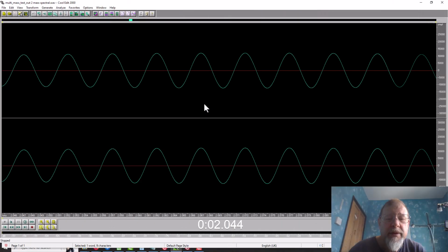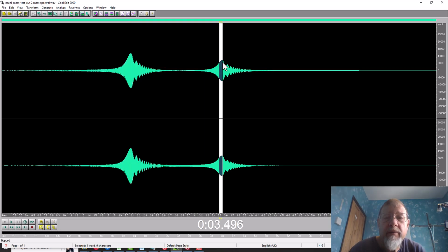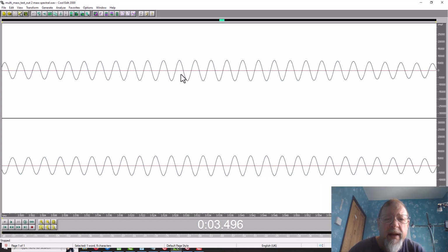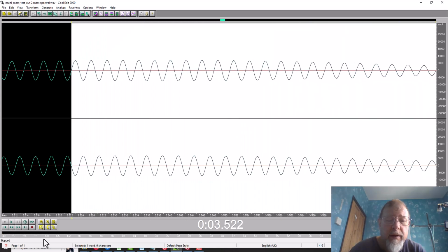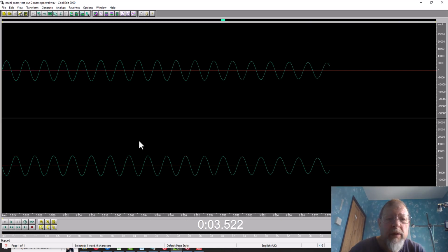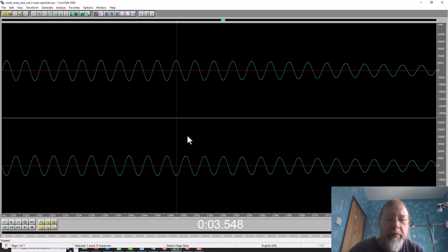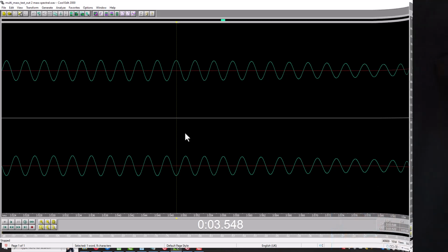And just to confirm, our 200 Hertz peak here, they are both going the same way with the same amplitude, whereas if we look at our 340 Hertz peak, let's just zoom in a tad more, they are going the opposite ways with the same amplitude. Okay, all good so far. So shall we look at the case of 3 masses?